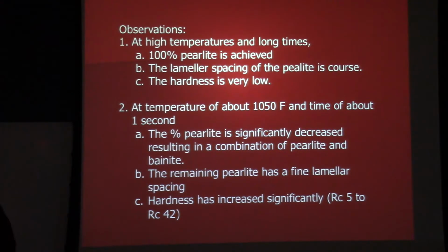Well, so, yeah, basically, if you don't form 100% martensite, remember that this is a different way of heat treating than we normally do. Typically, we're going to do a continuous cooling, or we're going to quench it in some bath. But in this case, we quench it down to a temperature and hold it. And as we get to lower and lower temperatures, what can't happen as easily? Diffusion. So with diffusion you get shorter range structures. And so bainite is a short range structure of iron carbide and ferrite.